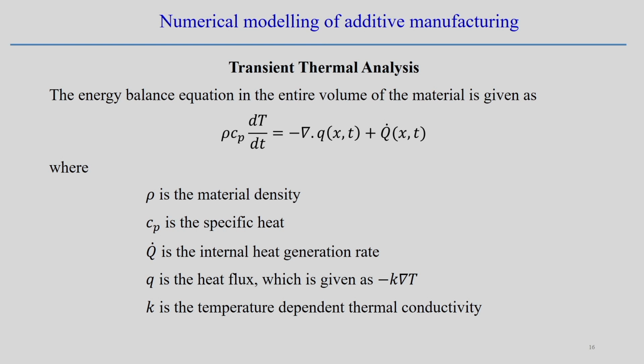But if you follow the finite element method, then you have to discretize the domain, you have to create the elements for the whole domain, and in that case you are assuming this can be the final shape and size of the domain. Then when you are depositing the first layer, gradually you keep on activating the elements. After deposition of the first layer and second layer, that element activation technique has to be modeled beforehand, according to a predefined path. So when layers are deposited, the domain size actually increases.